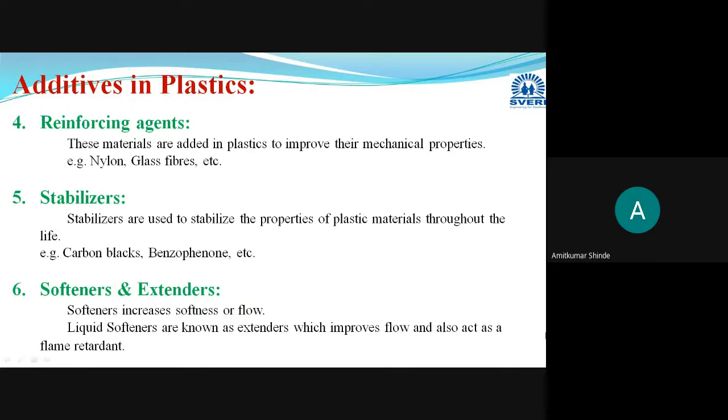In some units you have mentioned the strength, hardness. And if you check the properties of that same compound or material after a 5 or 10 year gap, it will remain as it is. To achieve this, you have to add certain chemicals or compounds that are termed stabilizers. In the case of plastic materials, we use carbon black, or benzophenone material, as the stabilizers.